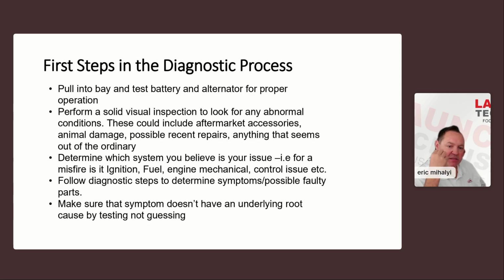And then I think the best thing, and I learned this from the famous trainer Jim Morton, is you've got to try and determine what system you think is the cause. He called it getting into the diagnostic funnel, getting as much information and getting into the right funnel as fast as you can. Looks like I have an ignition problem if you're chasing a misfire. It looks like I have an engine mechanical problem. I knew that because my volumetric efficiency was off during the test drive. Could I possibly have a control issue from another sensor?